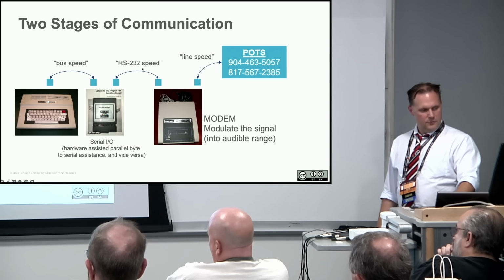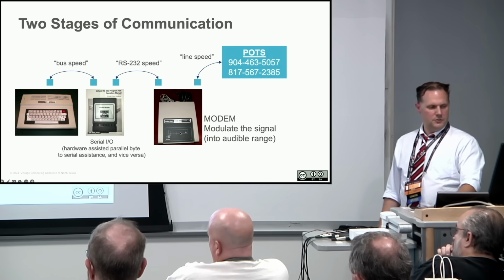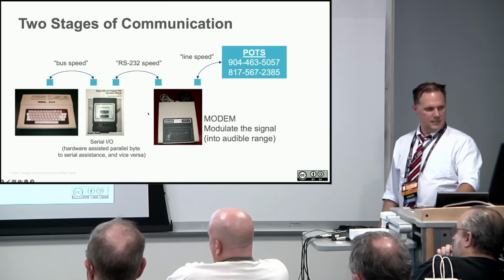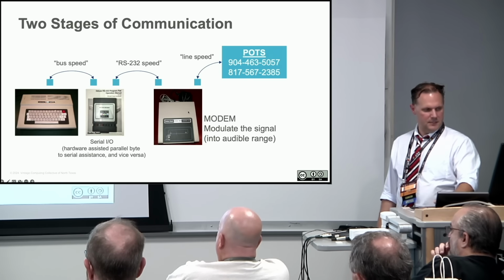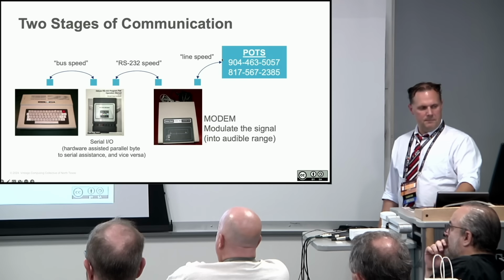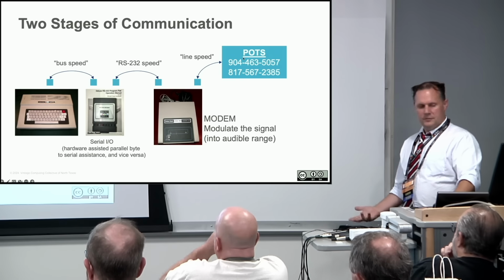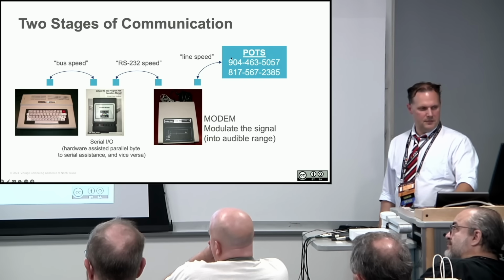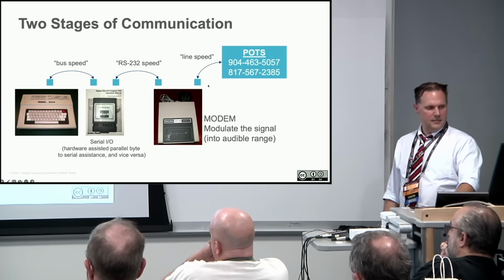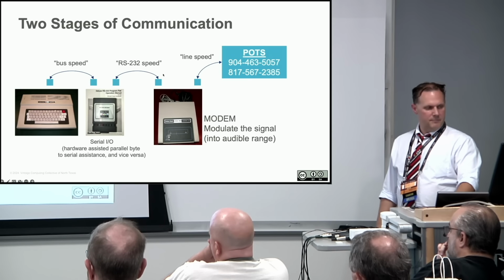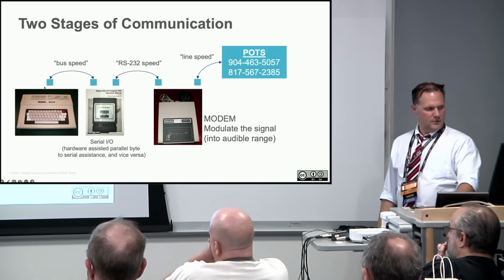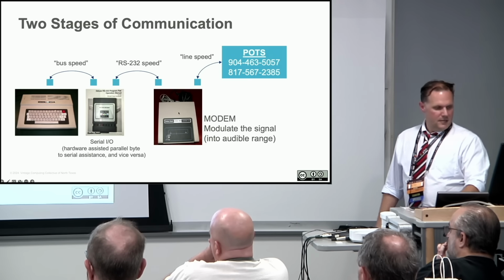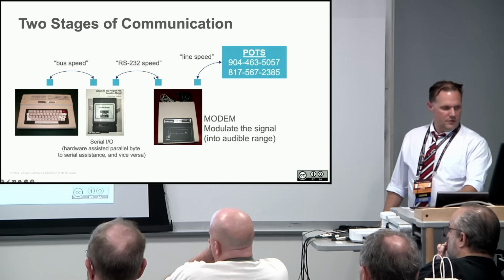Then through RS-232, it connects to whatever modem you want to use, and you would generally use a Tandy modem if you're using a Tandy system. You didn't have to use their brand modem, but most people with the Tandy systems did, just for price reasons. And then that handles the plain old telephone system. You got your phone number, and you're trying to call someone else's phone number, and the phone network handles all that. But the data comes in through your modem, back across the RS-232, and back across your bus, and shows up on your screen. That's one way that you can use RS-232.